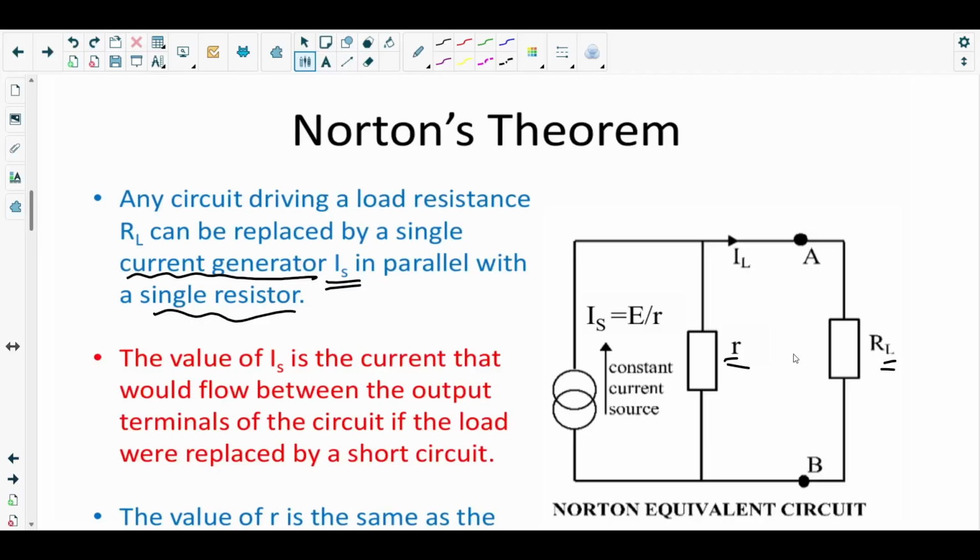The reason is, we learned from the Kirchhoff's laws that in a parallel circuit the currents get divided according to the resistors, right? So in the original circuit, if we want to find out how much current will be available for the load resistor, then we need to check how much current will be flowing through the load resistor specifically. Individually, how much current will the load resistor get?